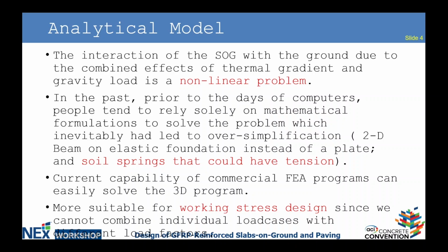because it cannot be superimposed. Okay? And obviously, the soil springs, in the past, people tried to come up with mathematical models to solve this problem, and inevitably, that would lead to oversimplifications with a 2D beam on elastic foundation type of analysis, and inevitably, they cannot cancel out so easily if the springs end up in tension. Okay? But today, most of the commercial finite element programs can deal with this problem. Okay? It's just an iterative process, and you have to define the compression-only springs.